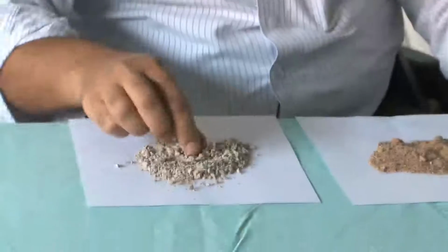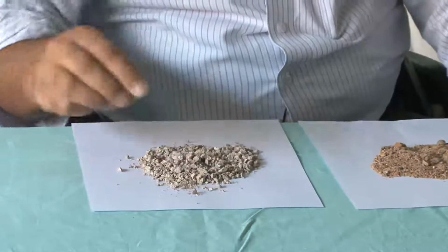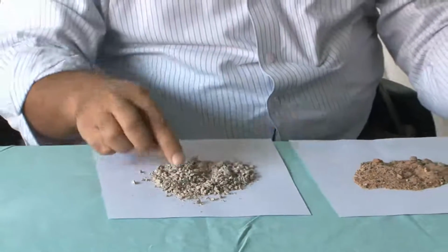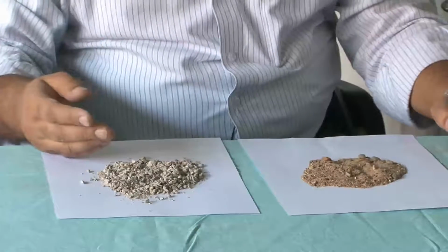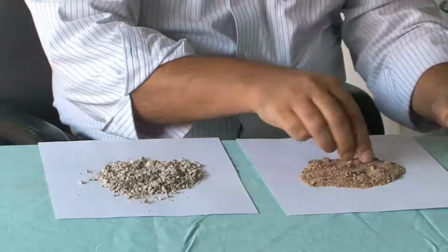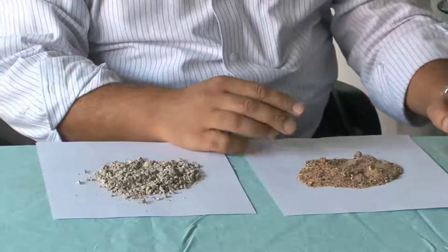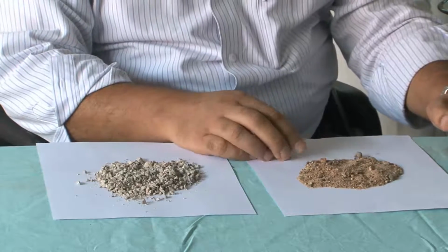Now, that concrete, if it is crushed, gives us something like this, and this again is a possible option against the naturally occurring sand. The naturally occurring sand is becoming more and more of a precious commodity, and we must ensure as concrete engineers to have a sustainable concrete, that is concrete which relies less and less on natural materials. So, if we can find substitutes, the better it is.